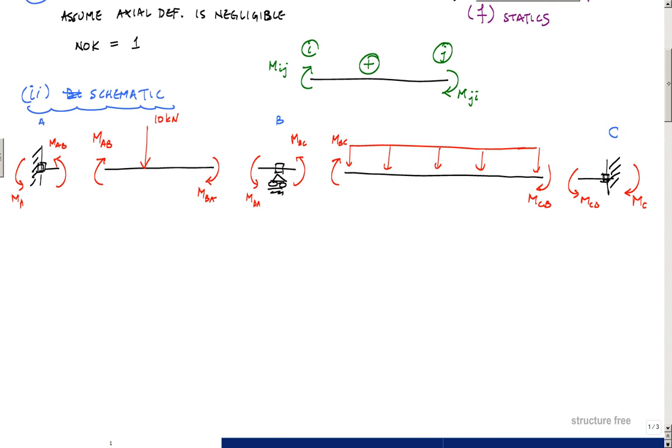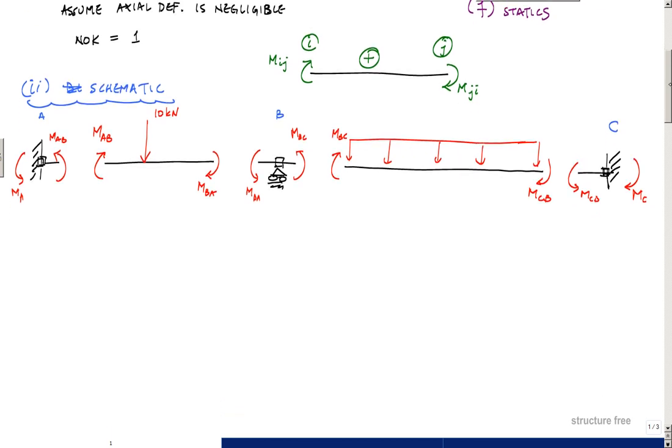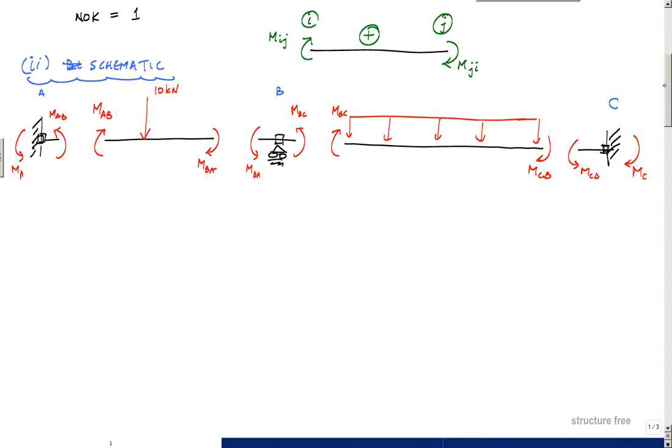The next thing I think in my process is to determine fixed end moments. So here are fixed end moments. And this is where you would use tools on the inside cover of your books, or just Google fixed end moments, and you'll see a bunch of drawings of fixed beams, something like this right here.